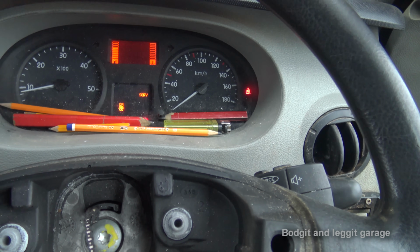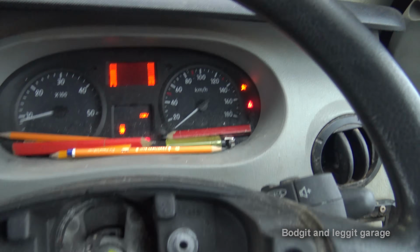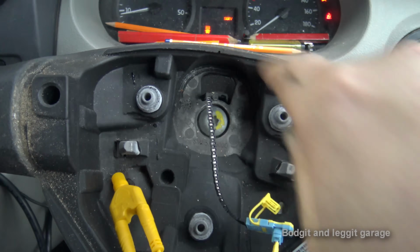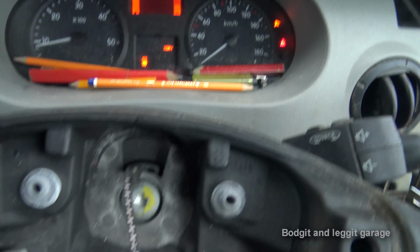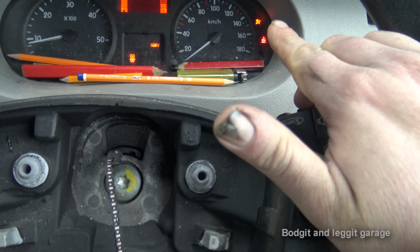Airbag light's gone off, but just now come back on again. So just be aware of that. It's no harm to spin the wheel, because if it is the clock spring, there could be a bad section in the clock spring. So you might put this on and the airbag light goes off and you think, oh, that's great. No, spin the wheel left and right a few times just to make sure that airbag light doesn't come on.